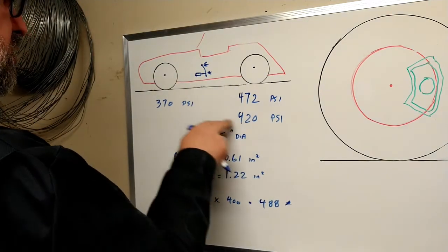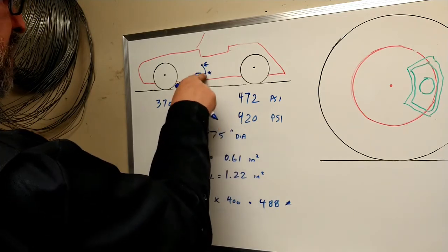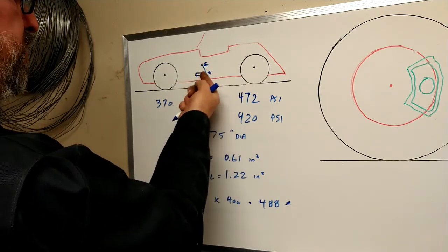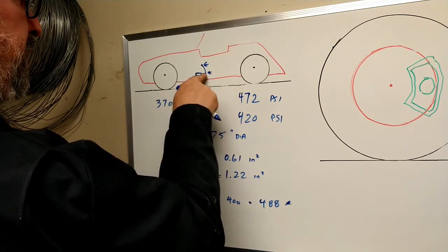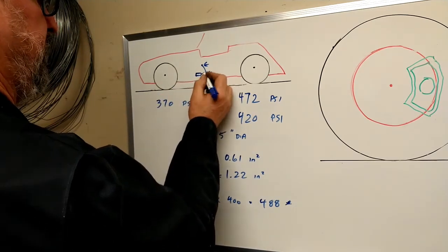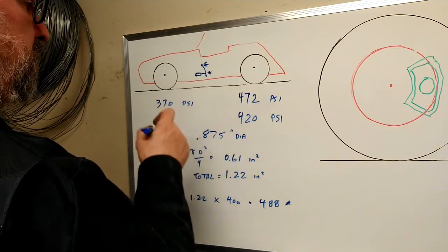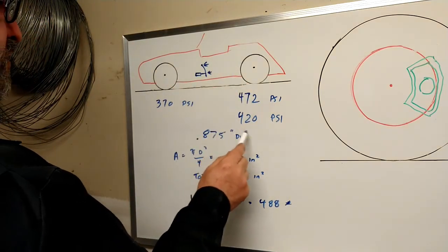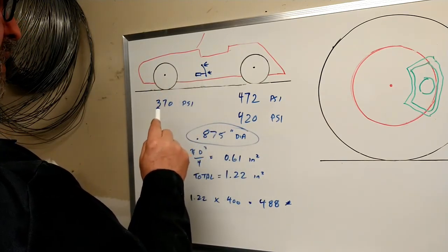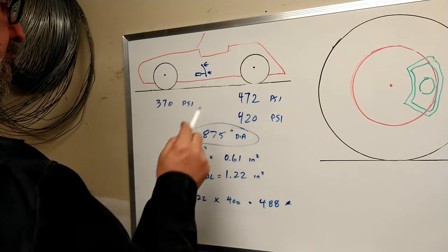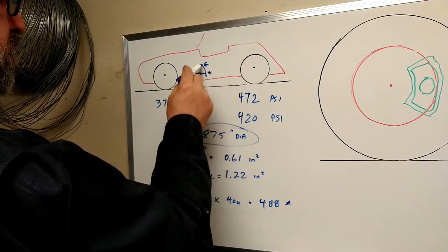This ratio is not quite exactly the same, but that is close enough that I can do that. I can modify that with the bias bar in the brake pedal itself. There at that pivot point, it changes whether it goes more or less to the front or rear cylinders. So I'm happy with this, with 0.875 diameter master cylinders, that I'll be able to stop the car easily enough. I can easily generate 100 pounds of pressure there.